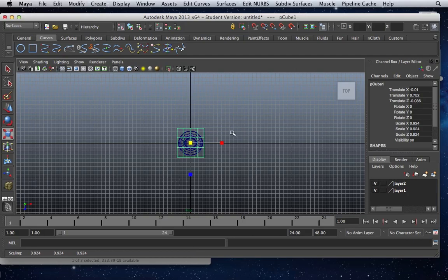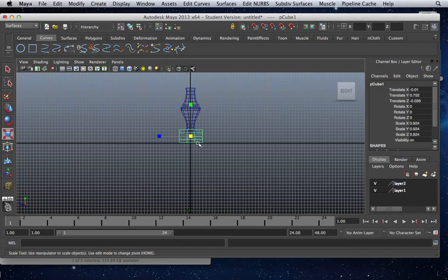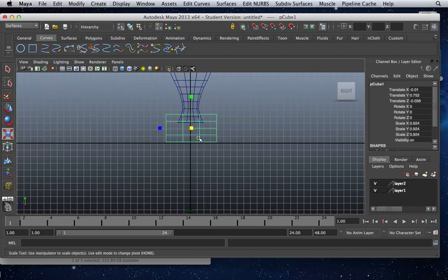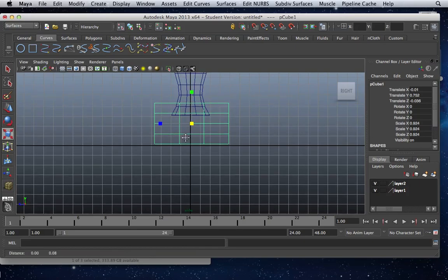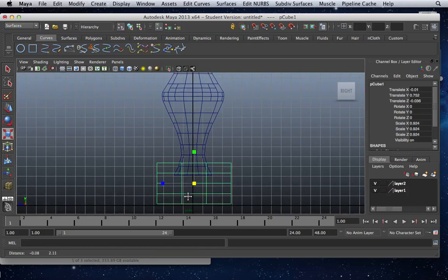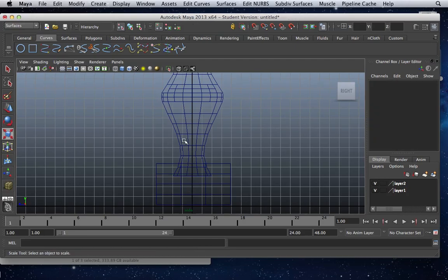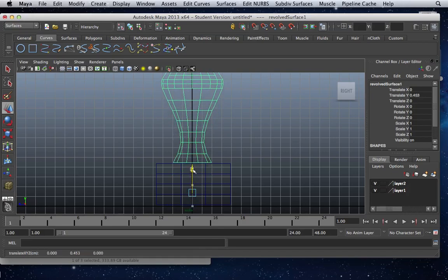And now I'm going to go onto the side view to see where our cube is located compared to our leg, and I'm going to zoom in by using the middle wheel in the mouse. Right now I'm holding command or control and using that middle mouse button, and I can see that my table leg needs to be moved in a little bit, so I'm going to hit W and move it up just a little bit.